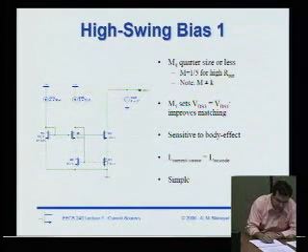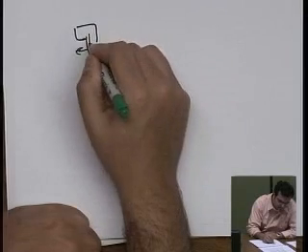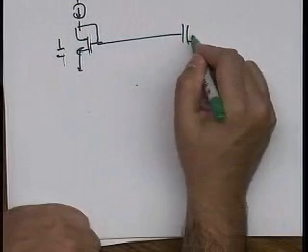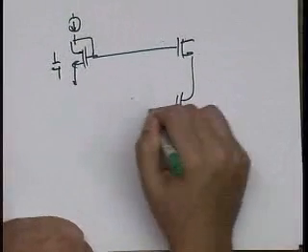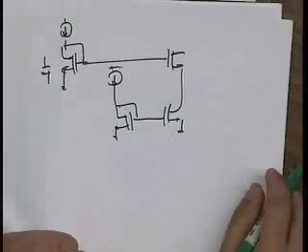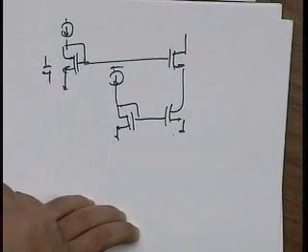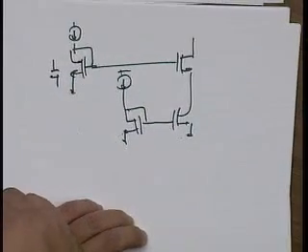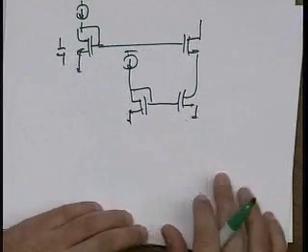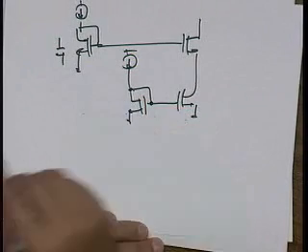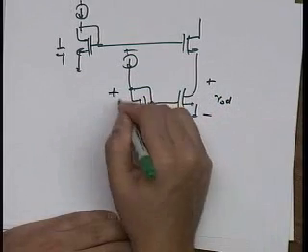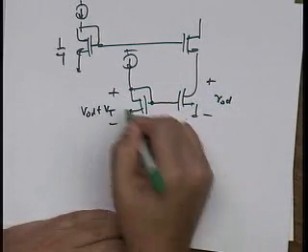So let me just redraw this simplified version of the circuit. This is 1/4 size. That generates the right bias for my cascode. And then for my mirror, I do that. This is even simpler, right? You might say, why'd you bother with all those transistors? Well, I can make this structure even better because I can get rid of the systematic error we just talked about with the VDS. The VDS of M1 is V overdrive, whereas the VDS of this guy is V overdrive plus VT.